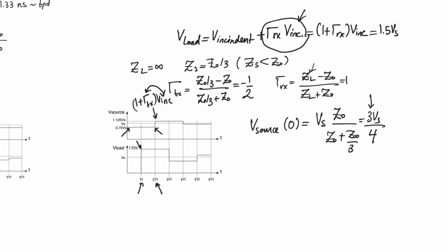Now, this component is going to reflect negative because we have a negative reflection coefficient at the transmitter. When it reaches the receiver after another time of flight, it's going to subtract from it. And so you will see this undershooting. And this will continue happening with the load reflecting back to the source and so on. And what's going to happen is that at the load, at the receiver, we are going to asymptotically, in an overshooting way, reach Vs. So what's the delay here?